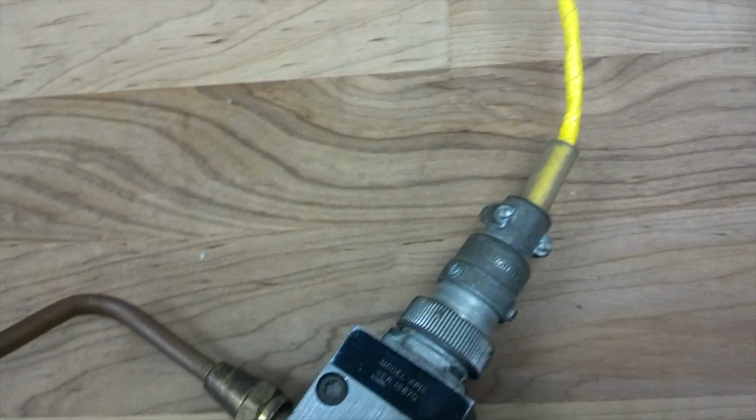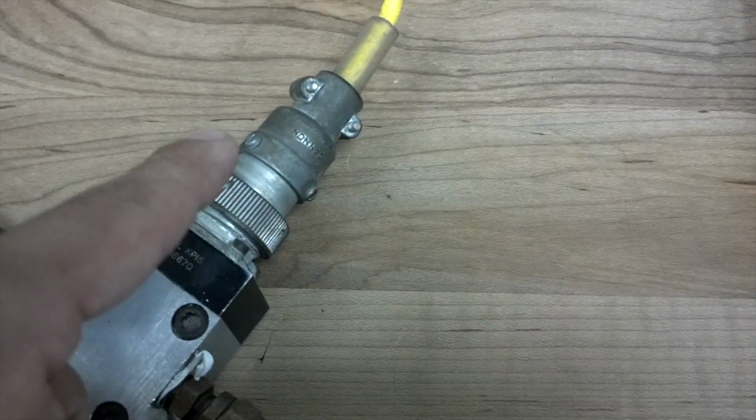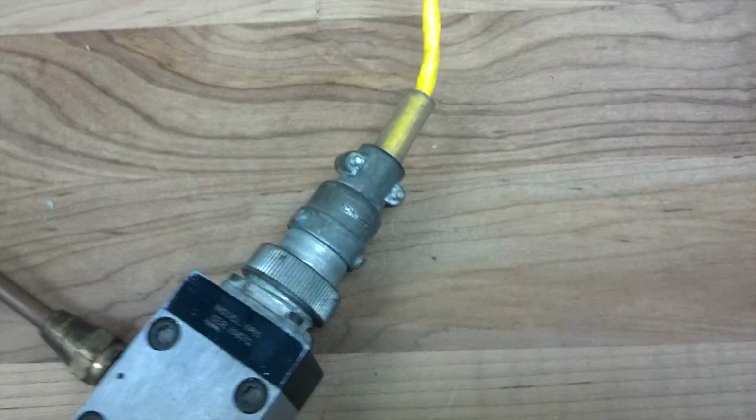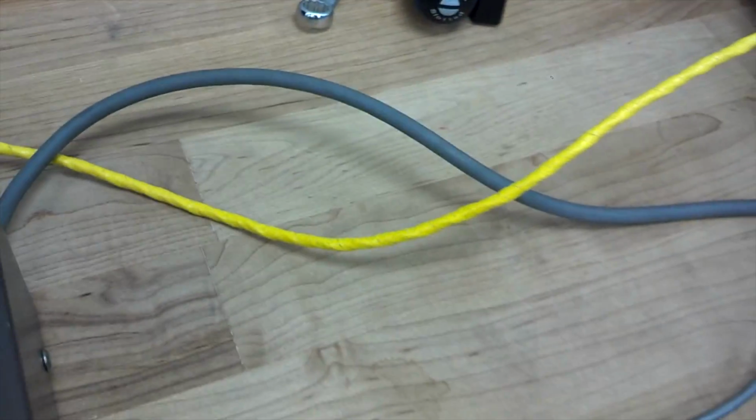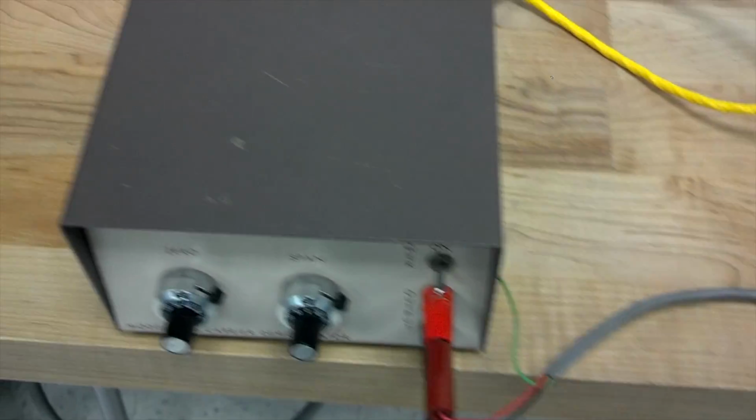The pressure transducer uses a piezoresistive strain gauge that outputs a signal when it receives a differential pressure. A strain gauge is a resistor that changes resistance when deformed. When power is applied to the pressure transducer, a signal can be read by measured voltage. What the pressure transducer is connected to is the Validyne CD15 carrier demodulator. This device can output a maximum of negative 10 volts DC.